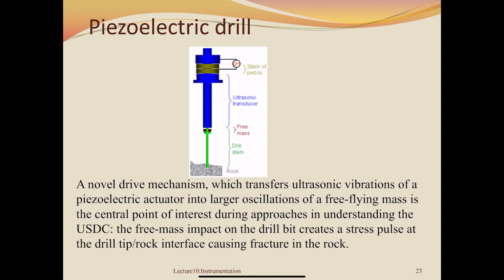Last one is piezoelectric drill, where we can see here we have a stack of piezo applied by the input voltage, and it will expand the material, and the effect is accumulated by putting a stack of piezo, then it will convert into large acceleration by the free flying mass. The free mass impact on drill bits creates a stress pulse at the drill top, causing fracture in the rocks.